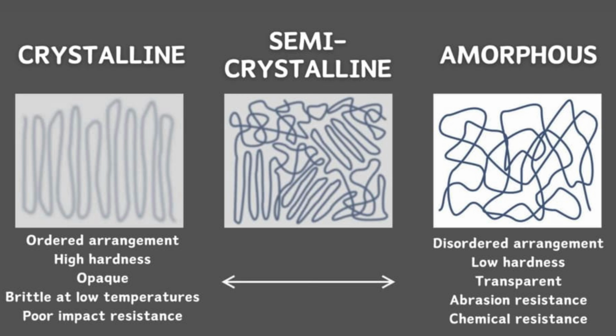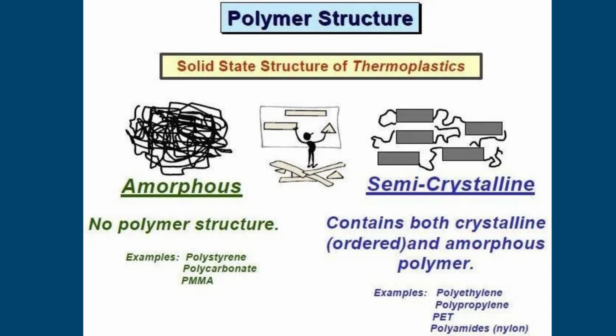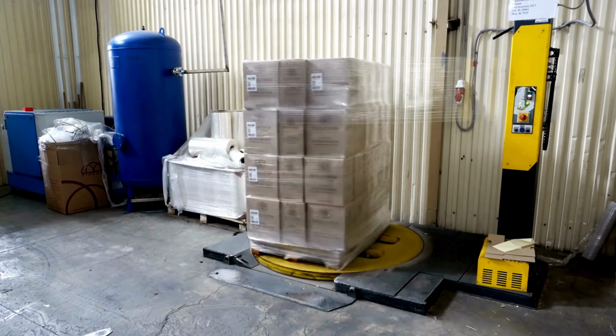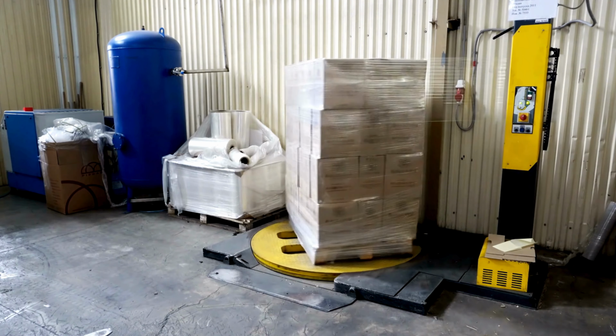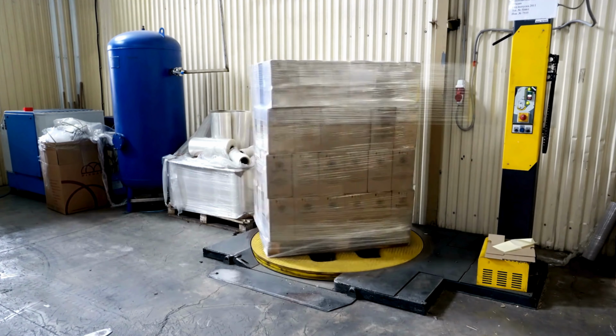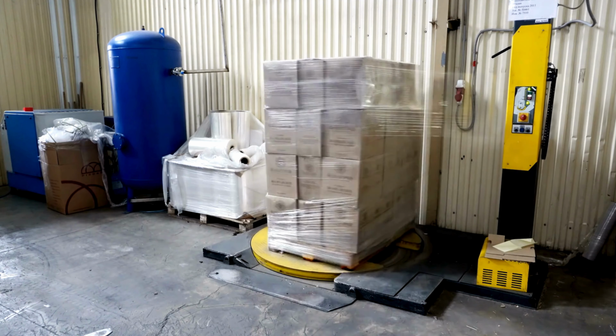Semicrystalline polymers contain ordered crystalline lamellae dispersed within an amorphous matrix. This two-phase morphology gives them a useful combination of stiffness, strength, toughness, and processability. Common examples include polyethylene (PE), polypropylene (PP), polyoxymethylene (POM), polyethylene terephthalate (PET), and polyamides.